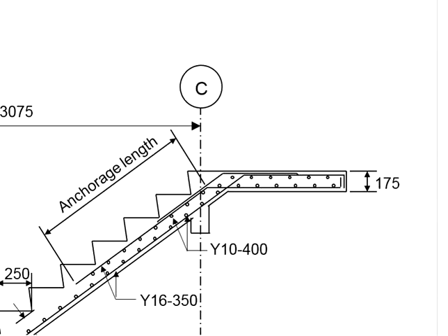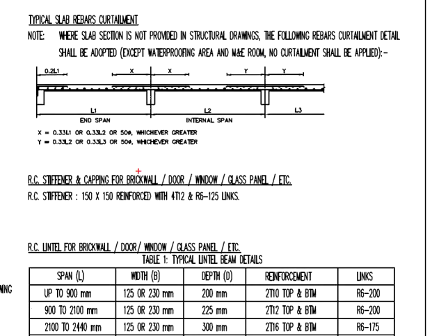The next question will be, how long will this reinforcement bar be? What is the required anchorage length? Again, I do not have the standard answer. Personally, what I will do will be again following the rules here: either 1/3 of the span or at least 50 times the bar diameter.